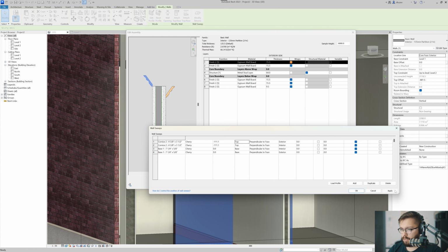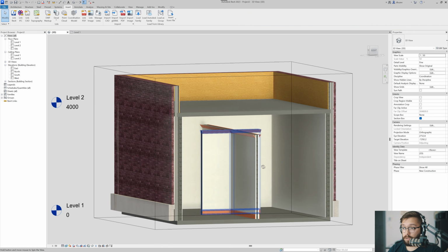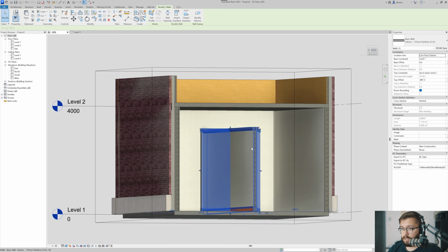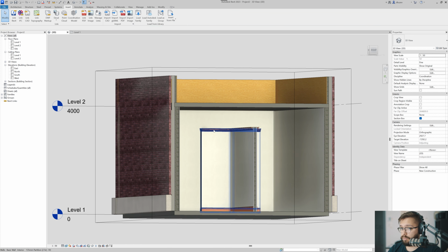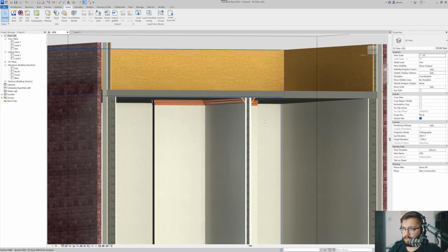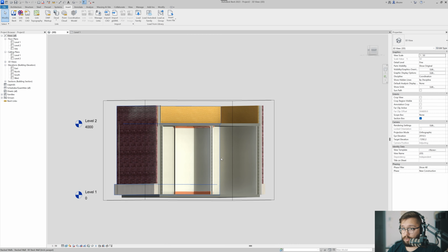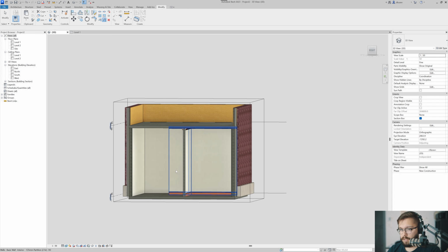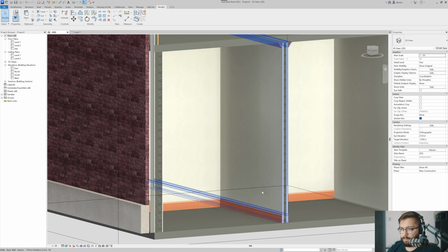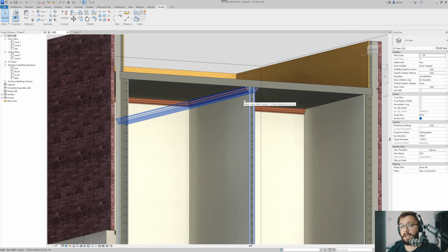Copy, paste, boom, good to go. I hit OK, boom. So now I have cornices, right? So if I take these two walls and if I bring them to, so here's the attached top and base, and I'll just set that they attach there. Boom. So now my walls would always have cornices if I just extend them to there and then, okay, sure, there. So this is how you can use the sweeps, okay, to build them in.